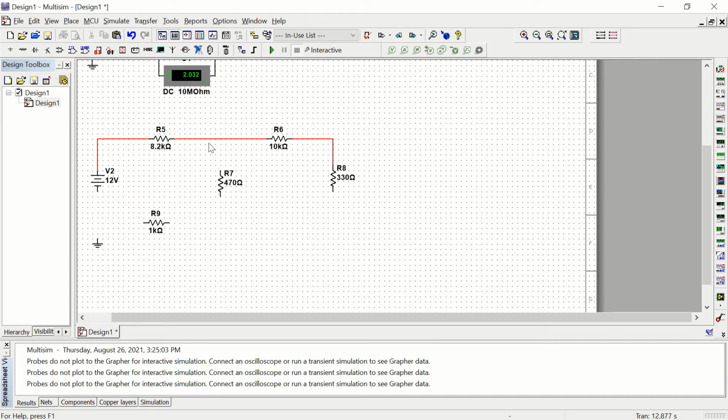Now notice I can't get a joint there, the junction. I can get one if I run it from the resistor up there. I can get it, but I can't just generate a junction. So I'm going to come down here, and then I'll have to connect that in there, and we'll connect this to ground, and then, okay. And then I can hit that little play button. Oh, I built the totally wrong one. I built the one from step 5 with all the wrong resistances.